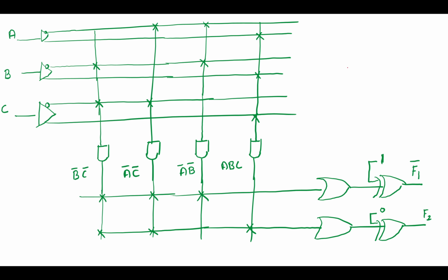And now the implementation part, we are reducing the complexity, we are not taking more number of logics. So this is a NOT gate. Okay, if you apply a here, this provides you a bar. If you take one wire here, that is a. Okay, so all these AND gates are programmable. Suppose that this is first, second, third, and fourth. This is all programmable. Why is it programmable? Because here there is a fuse on the wire.